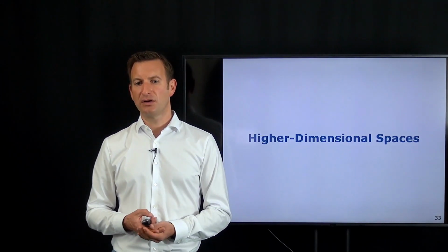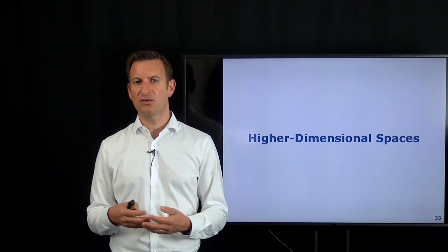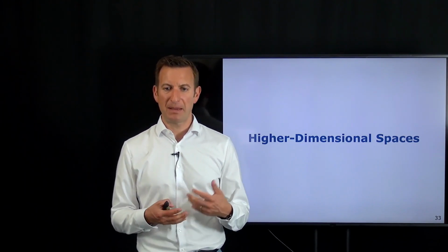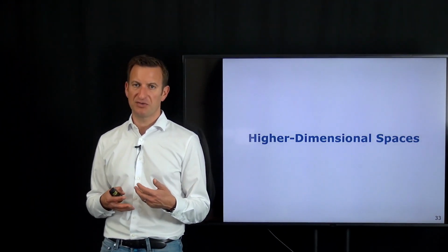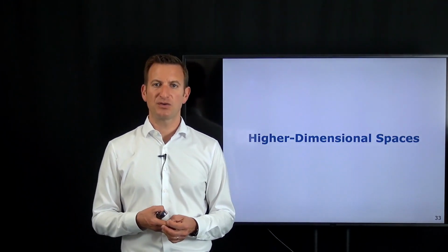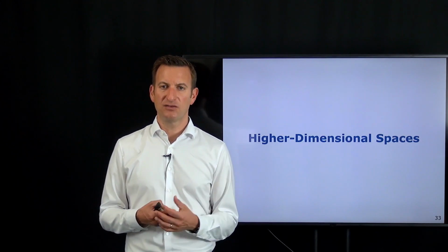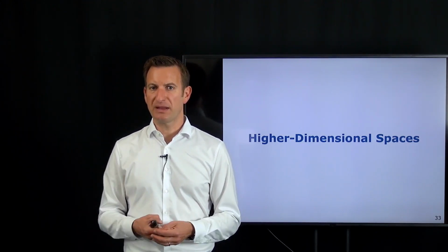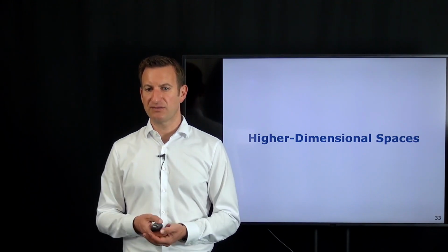We can, however, also go a step further and try to integrate this path execution or collision avoidance by planning in higher dimensional spaces, as long as we can execute the planner fast enough. So what do those higher dimensional spaces look like? Again, so far we just considered the XY space, but in reality the orientation of the platform matters and also the velocities of the platform matter.